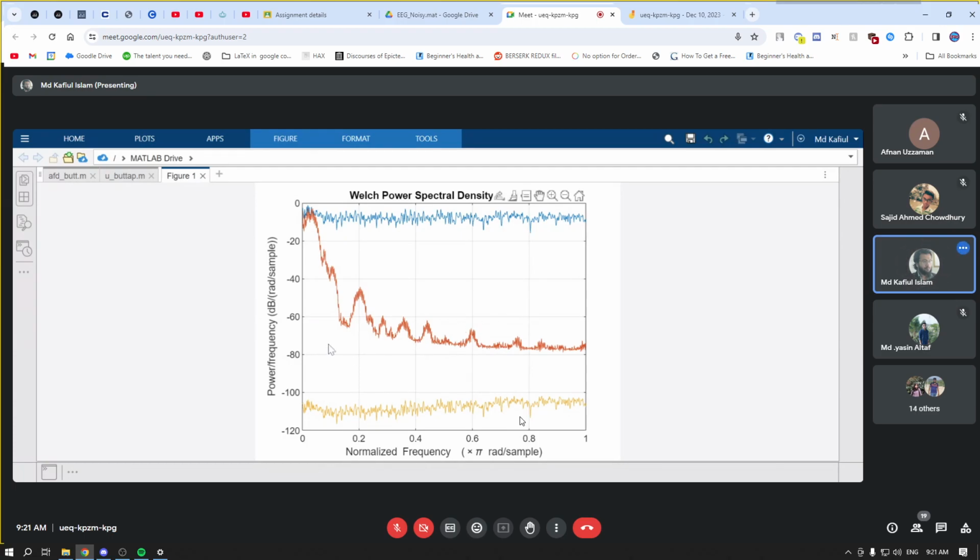We said it was supposed to be a low pass filter, but somehow the power in both the pass band and stop band is very low. When you think about a low pass filter, we expect the power to be highest in the pass band and lowest in the stop band. We designed the filter at 0.1 pi angular cutoff frequency, but still it is actually the similar thing.